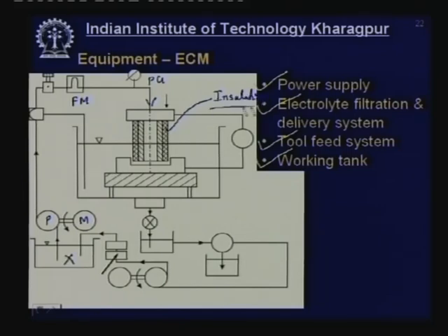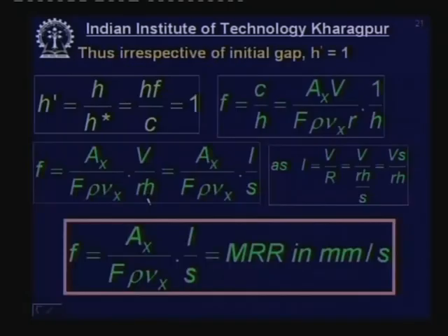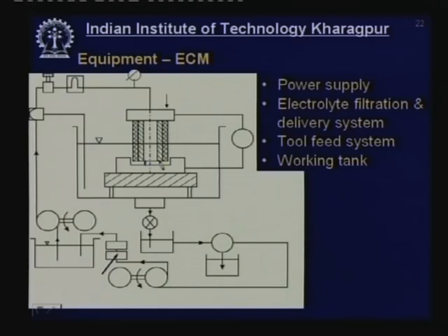You may ask me why we are going to provide insulation on the outer surface. We do not want an overcut. So, the electrolyte comes like this and moves over the working surface, and gradually at this particular place you would have electrolytic dissolution.